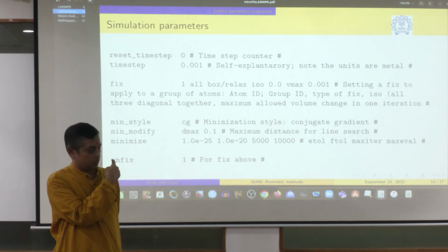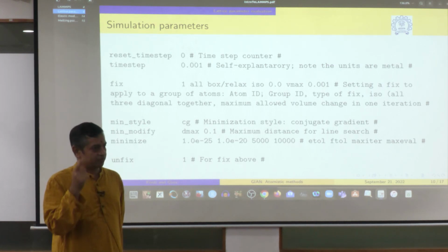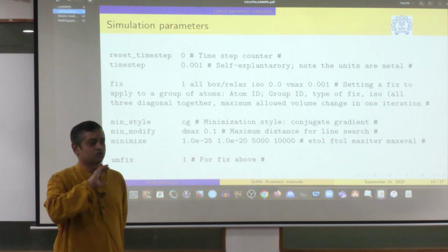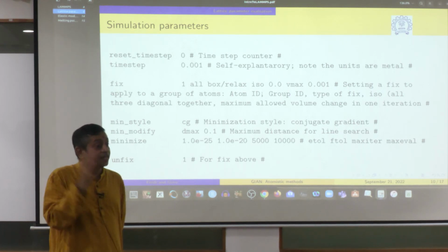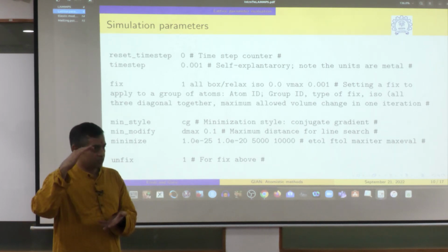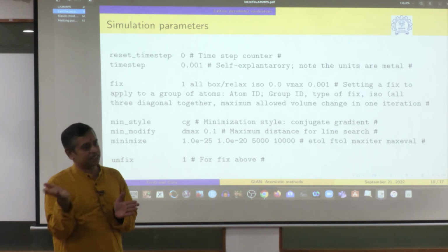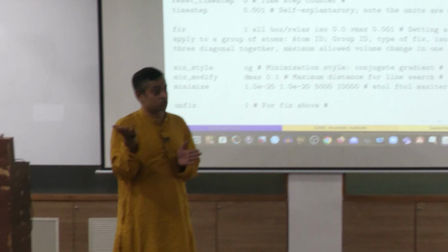Okay, this is at 0. But we can calculate at other temperatures. You can run an NVT, get to 300, keep the system and equilibrate, and make sure that it has equilibrated. Now you start measuring the box size. In fact, we have measured up to the melting temperature. We have calculated the lattice parameter at near about the melting temperature also.